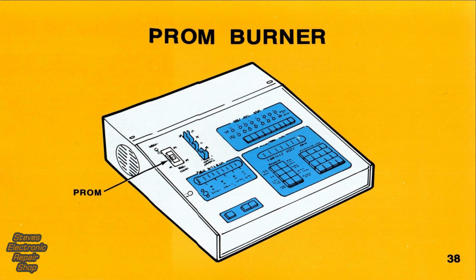Here we see the PROM programmer, called a PROM burner. The PROM is plugged into a socket, and the program is entered with the keyboard. Electrical impulses blow the fuses, burning the program into the PROM.